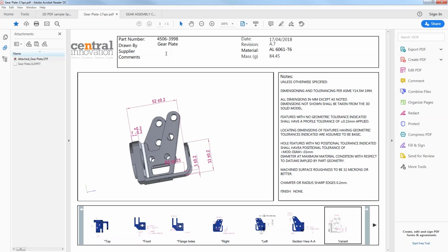So let's say you send it to the supplier, the vendor, or to your manufacturing plant, and they want to know, okay, what is the surface finish, or what is the paint to be used. They can add this comment directly right here and probably send it back to you. Again, MBD is completely controlled within PDM. So all the PDFs that are being spit out can also be version controlled using your PDM environment.